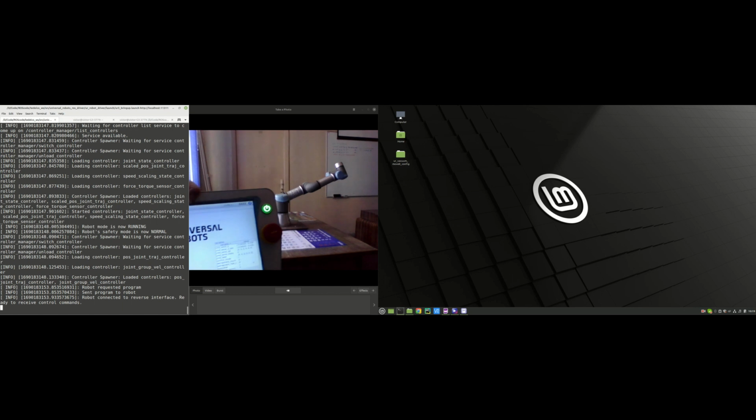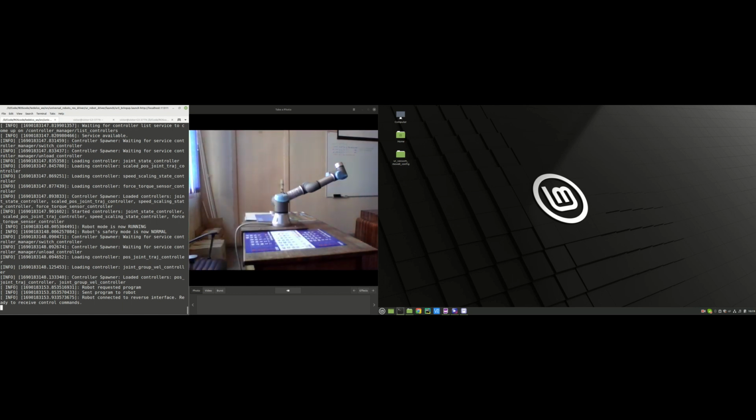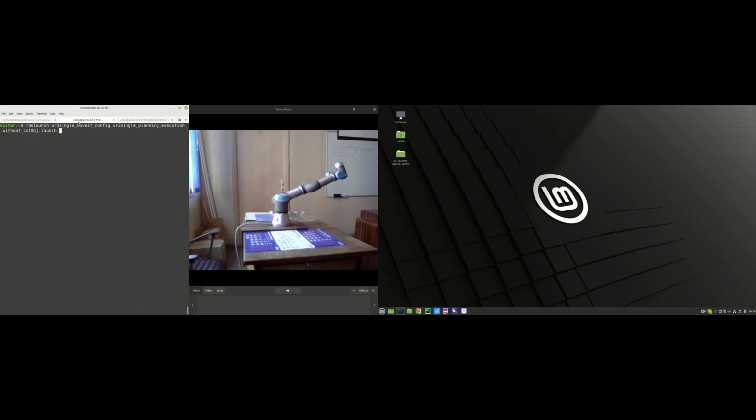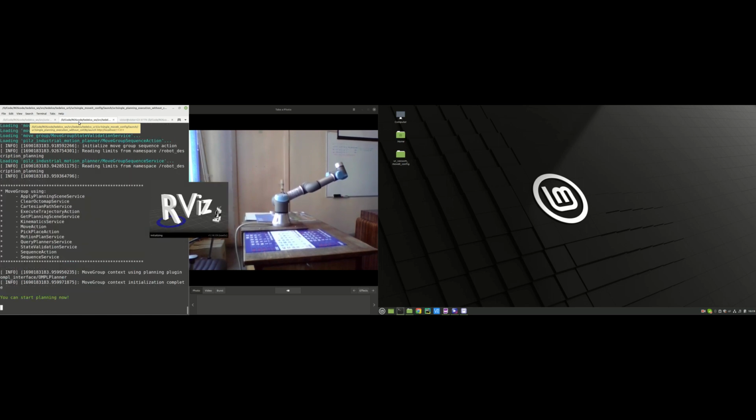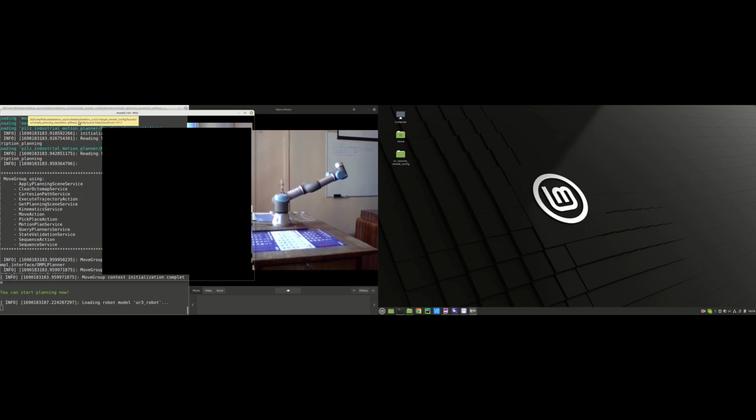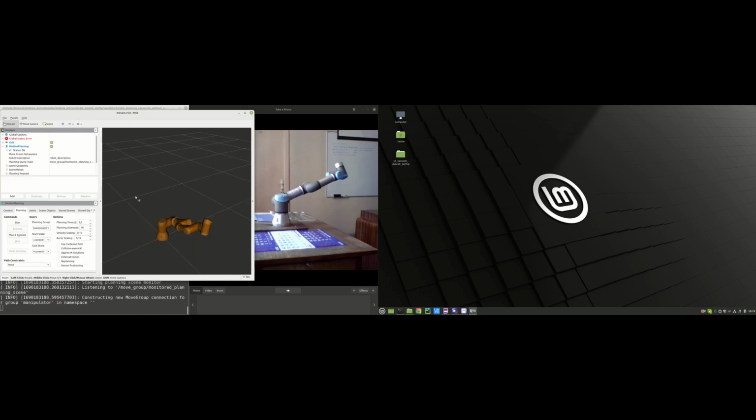We also must start a UR program on the robot for the operation to be complete, and what I've just showed are the possible topics we can work with after the process is complete. Once we have the connection ready, we can start Moveit by launching Rviz together with the motion planning plugin and some other helpful files which makes Moveit complete, such as planning context.launch and movegroup.launch.